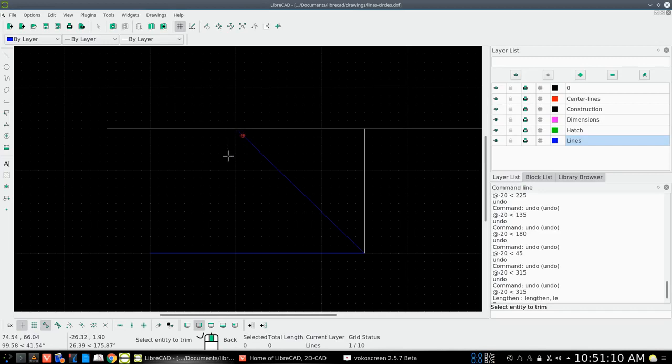Okay, let's right click to remove that tool and release the limiting entity. Now we've got a point here. Okay, so that's exactly what we wanted. We are actually 45 degrees to 15 units high. That way we didn't have to calculate the length of this hypotenuse angle.